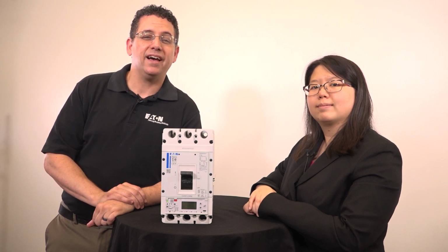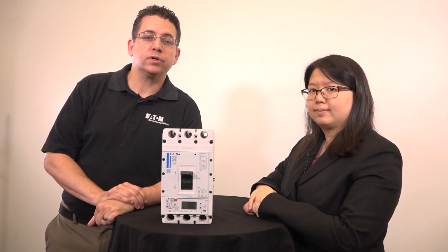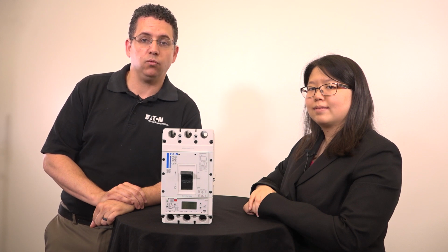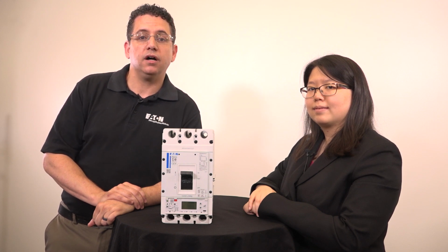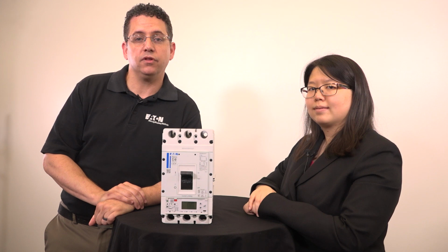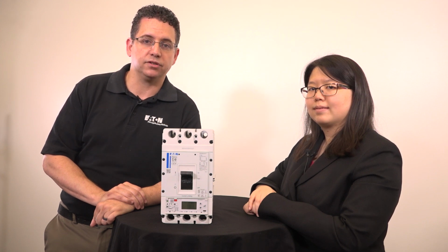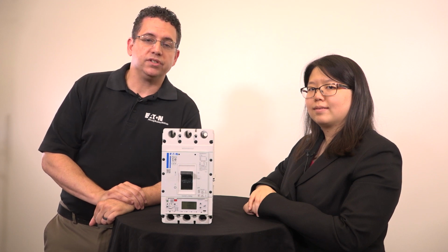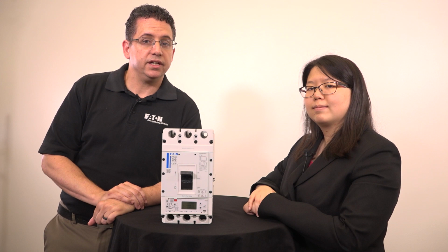Thermomagnetic trip units have simple protection features that people expect from their circuit breakers. For example, like getting warm when the breaker trips. If the breaker trips a lot in a short amount of time, they get really warm and stay warm. The physical properties of the trip unit mimic the thermal heating of the load cables and make the breaker trip faster. It's almost like they remember the heating in the cable and that they tripped recently, hence the term thermal memory. The downside is this.